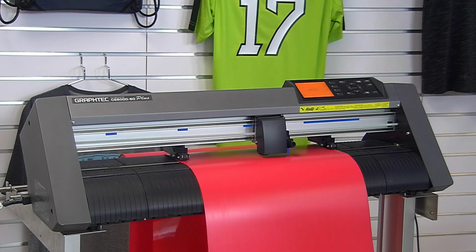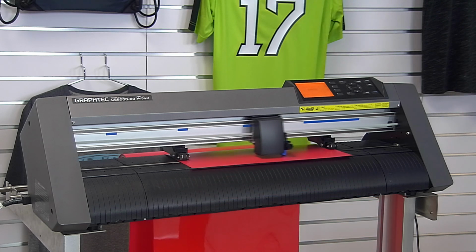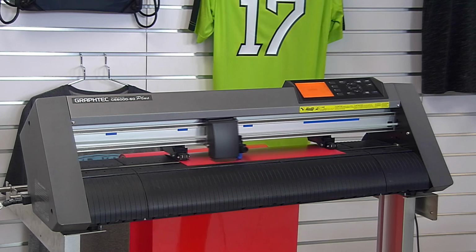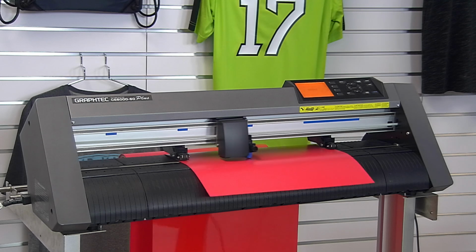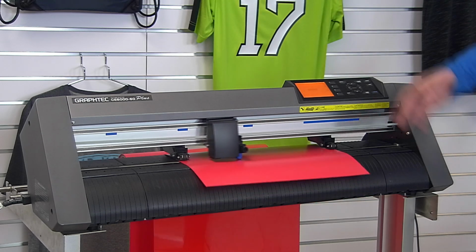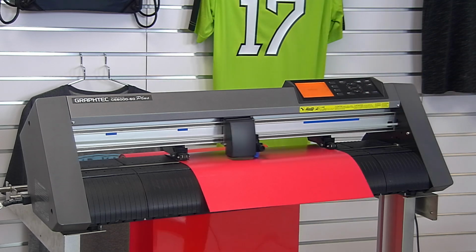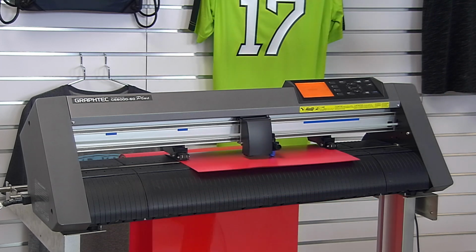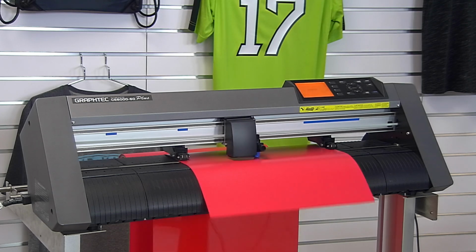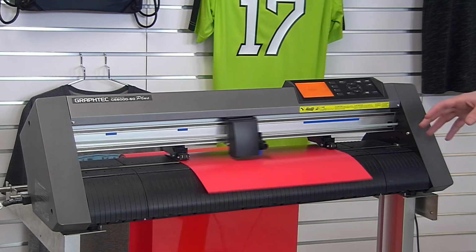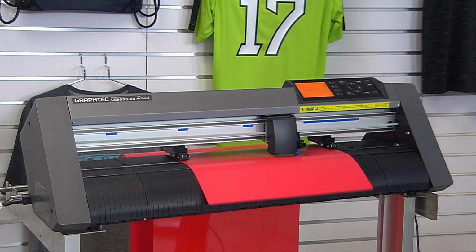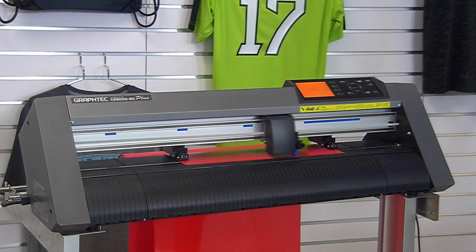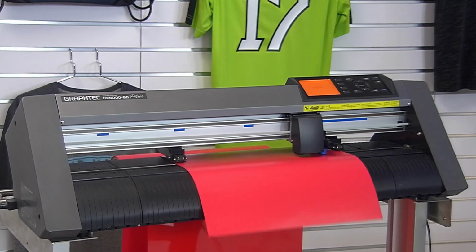I have a pretty sharp blade in there. ThermoFilm is about 180 microns thick, which means it's like double the thickness of your standard material like a fashion film or premium plus. I have the speed set at 20, which is centimeters per second, which is a little bit less than half as fast as the machine can go. Don't like to press the limits because this is unattended cutting. I'm going to be working on something else, and I'm talking about finishing it a minute sooner just by cranking it up. I'm fine running it this way.